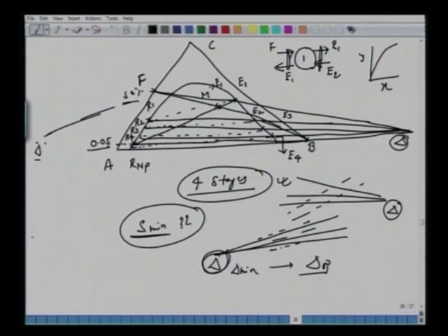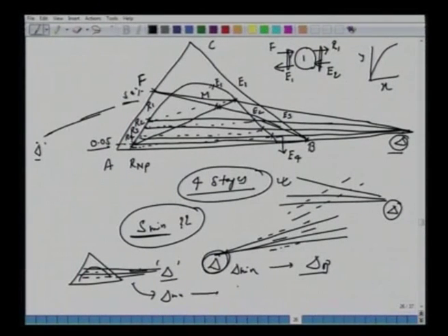All right. So of course in this example, all operating lines, we have the delta on the right hand side, tie lines are like this, or in some cases it's possible, say in a different system, when the delta is on the right hand side, and we have all operating lines going like this, but the tie lines are also downward. So there also we should be careful of obtaining this delta min first and then getting this operating line. All right.